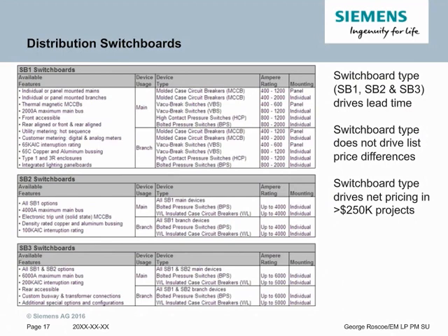This involves 2000 amp through bus and below, 65 kA interrupting rating and below, temperature rated copper and aluminum only, thermomagnetic molded case circuit breakers, basic meters, and fuse switches. SB2 switchboards have all the features of SB1, add electronic trip circuit breakers including our WL power circuit breakers, go up to 4000 amp through bus and 100 kA. SB3 is everything else. It's 5000 amp through bus, 6000 amp main bus, 5000 amp main breakers, rear accessibility, custom designs, and any special manual modifications to be made.